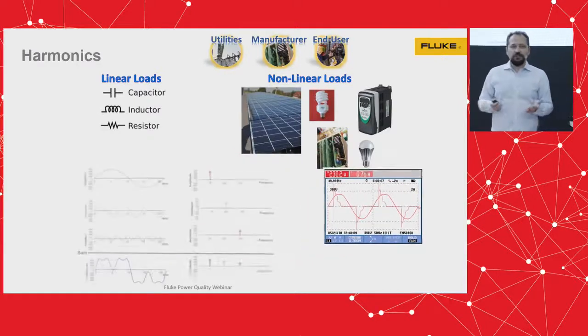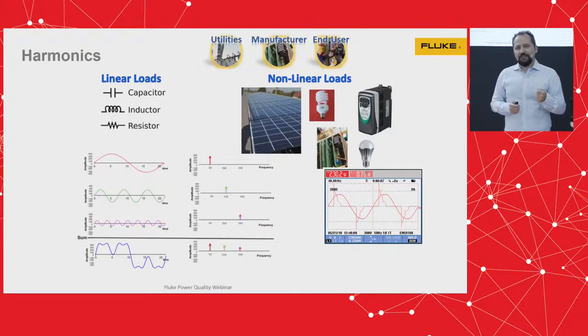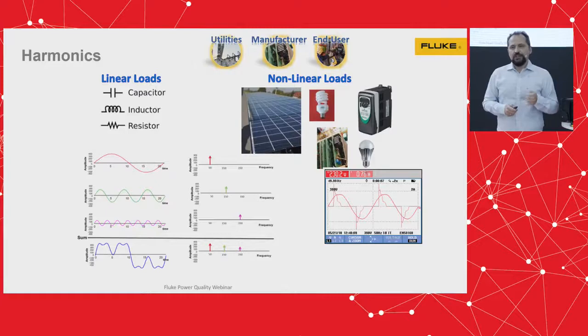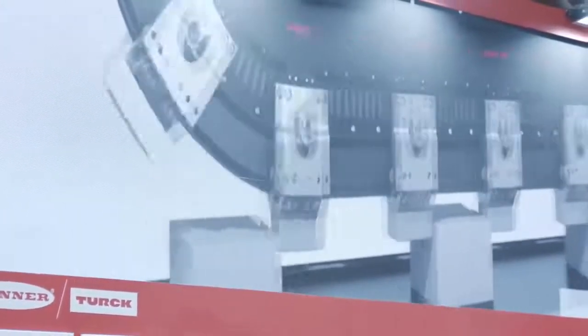So we need to be able to sample our electrical signals really fast, to be able to diagnose which harmonics are creating the issues that we are seeing and take the appropriate measures.